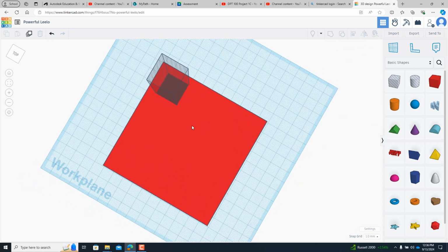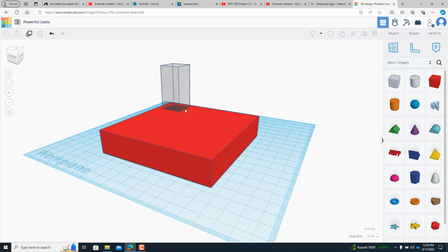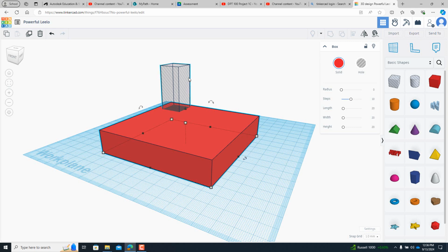And the thing of it is, what it does, this right here is your cut. This was what they'll call the join command a little bit later on. Or extrude, but this right here is your cut command, okay? So to get that to cut that piece out right there, all you have to do is simply hit your shift button and click on this solid, okay? And then with your shift button held down, you haven't ever lifted your finger up, you've got it held down, you click on that.